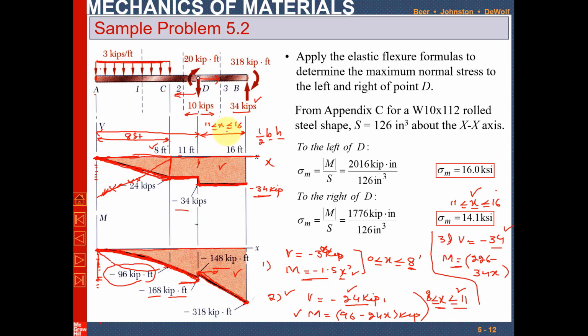So we have the moment before point D and after point D, and we will put them in the flexure formula in order to calculate the stress before and after point D.